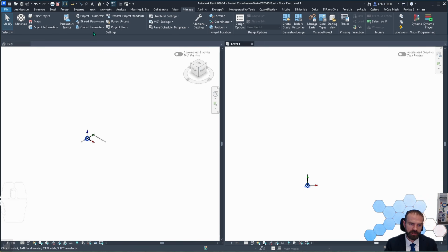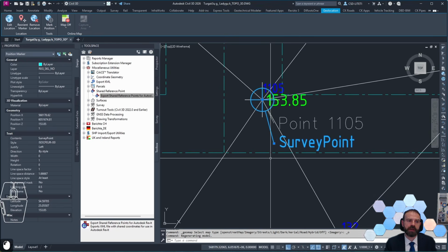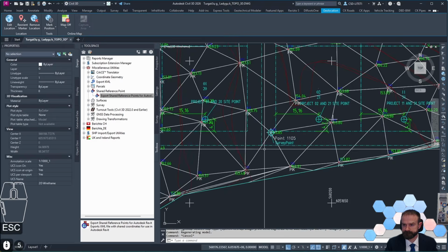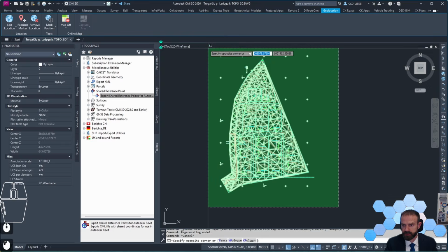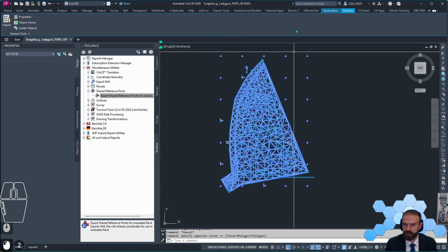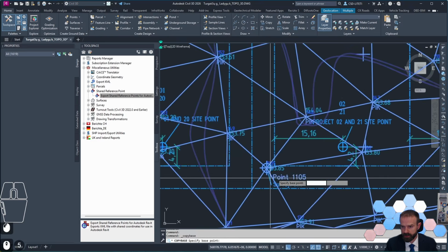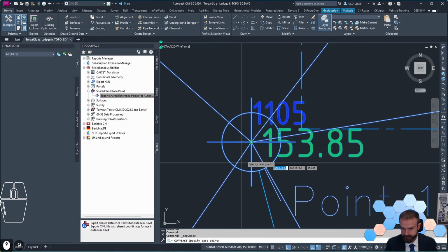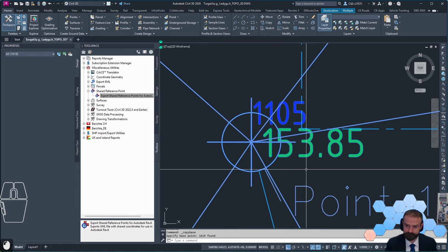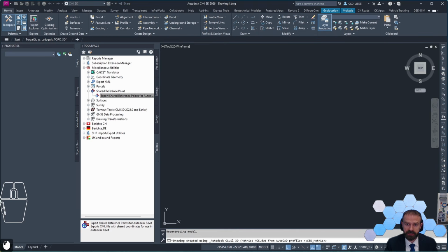Now I will import the file which has the project local coordinate system. So I need to go back to Civil 3D, and I need to select all these components and go to Home and select Copy with base point. And now I should go to this location and select the base point of my copy. Now I click New Drawing.